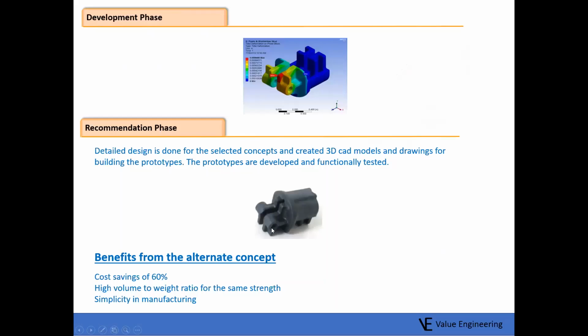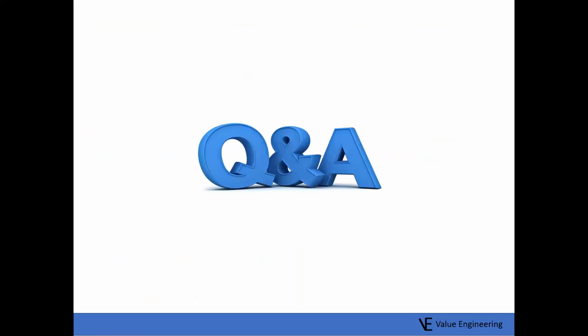This is a threaded portion. Small screws will go in, one from here and one from the opposite side, at the time of assembly. And then it will give the movement to the jaw with this pivot section. That's why it is called a pivot. So that's why we got this cost reduction there.